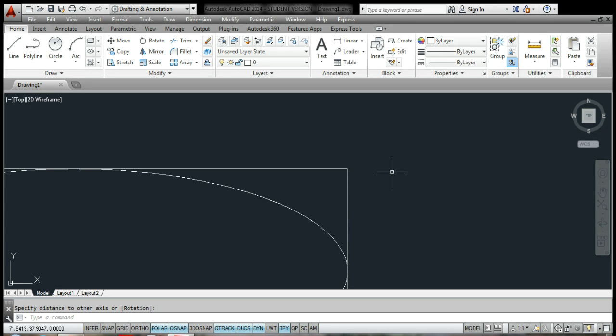Now I will do the fillet command, which is F-I. Actually, just an F. Alright, so I'm going to come down here and click on radius. Give it a 2-inch radius. Click on this first line and the second line because I want it applied to this corner. And you can see it pop up right there. And there is my 2-inch fillet.